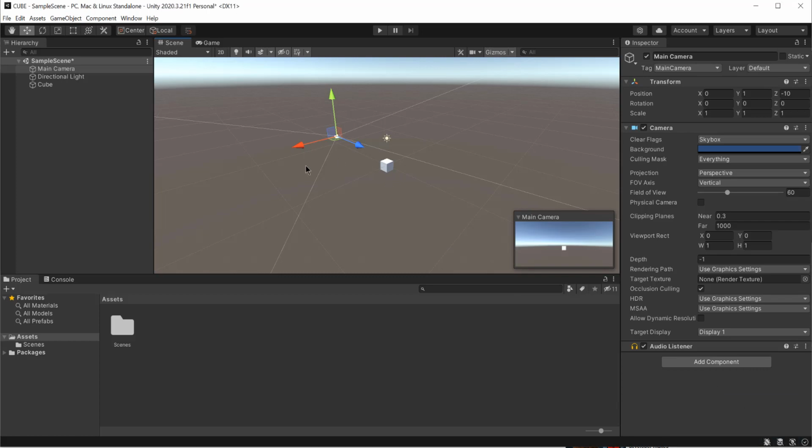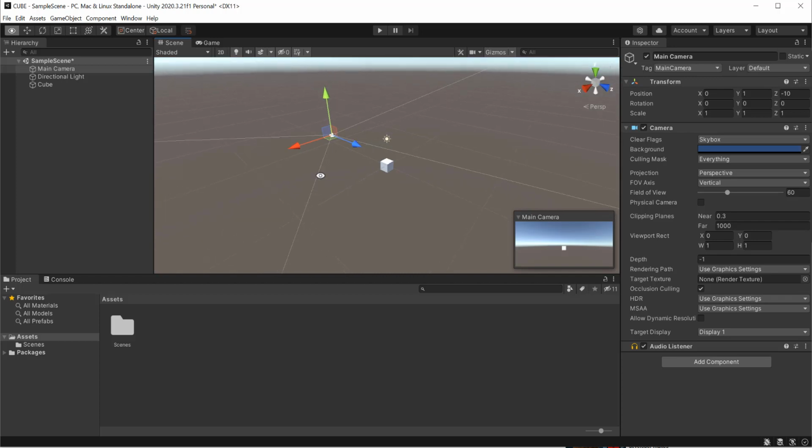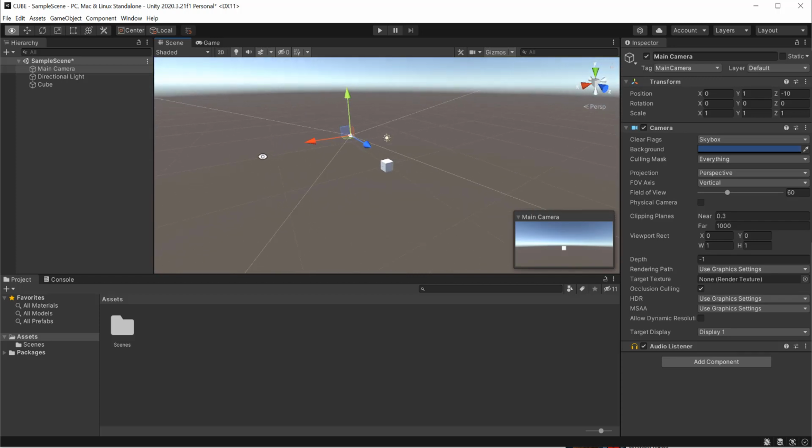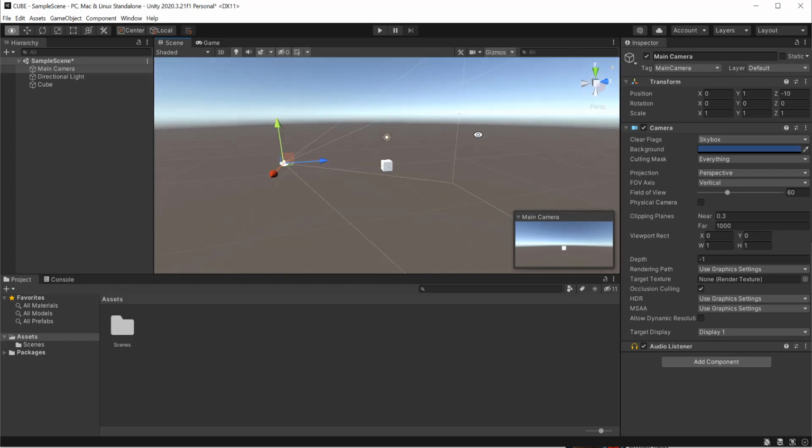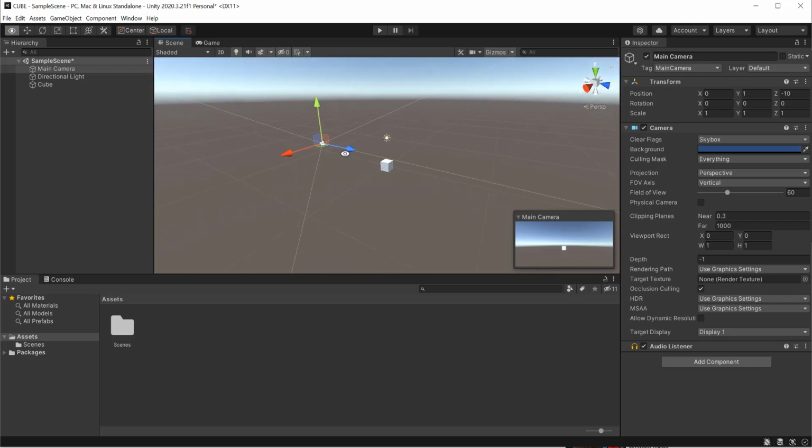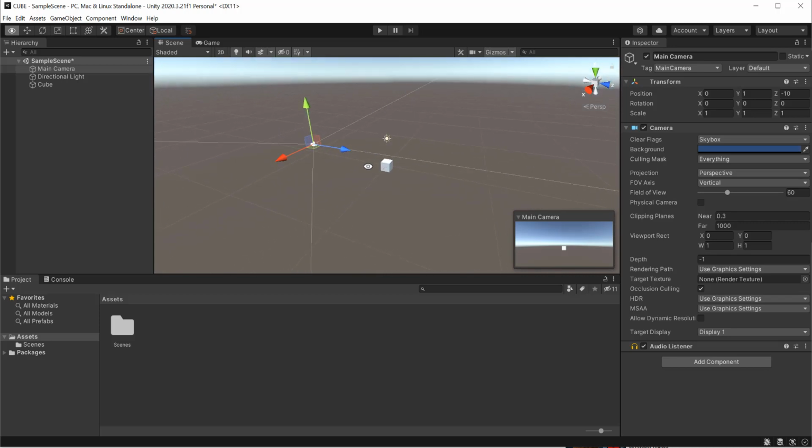So he's now demonstrating turning. Hold the Alt key and the left mouse button and it enables you to move the view around in the scene. And we'll move the directional aspect of this, holding onto this, and you get close to the cube and the cube gets bigger and it sees the top of the cube there.